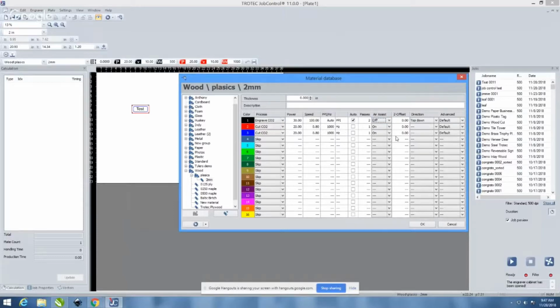John, can you just touch on why it's important to have on for cut? Yeah, most materials, if you don't have it set to on, well, there's 2 things. First of all, your material may flame up, so that's certainly the case if you're trying to cut engraving plastic or acrylics or rubber. The second thing that's important too is to make sure it's on to protect the lens.